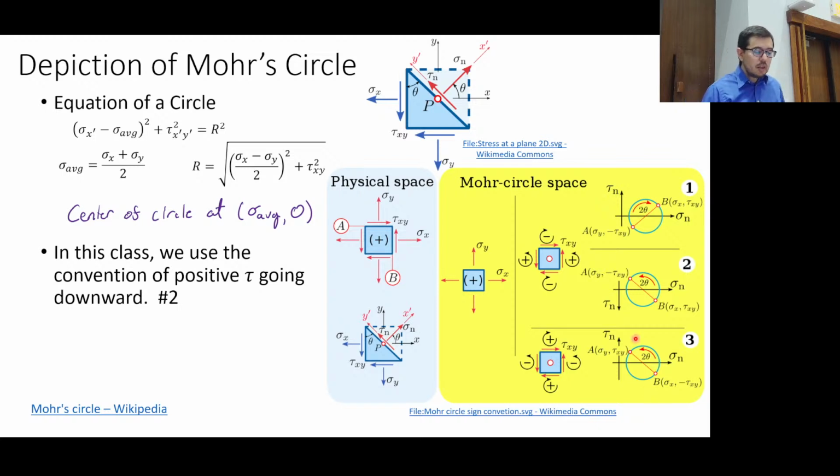The rotation we see in the Mohr circle of 2 theta, and you've already seen 2 thetas, in the sine 2 theta and cosine 2 theta of your transformation equations, ends up being counterclockwise if you do tau downward and follow this theta stress. If tau is upward, then the 2 theta angle is going to be clockwise, so it's the opposite direction.